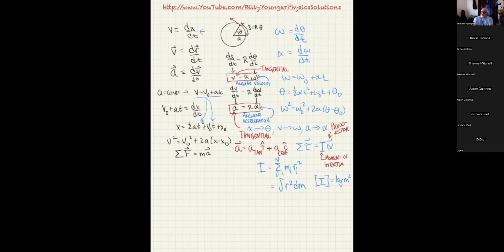And they need the freedom to try different materials. So for instance, if I decide to have a beam hold up the roof above a doorway, I get a different strength if I use the lumber called SPF, which is spruce, pine, fir, than I do when I get, say, southern yellow pine or poplar or something like that. Or better yet, what if I use steel? I get an entirely different strength parameter.